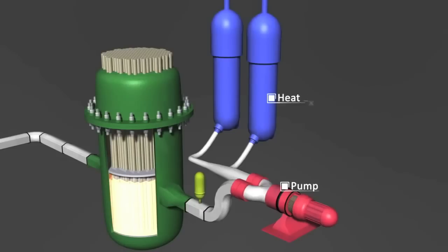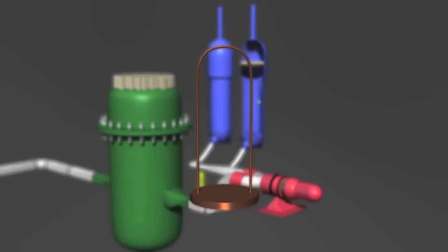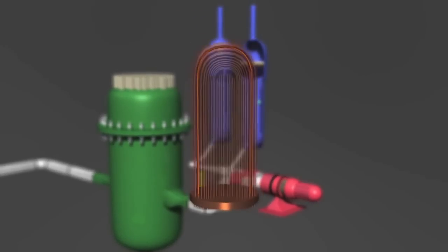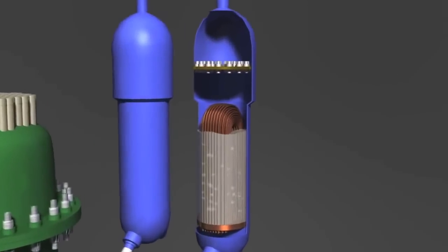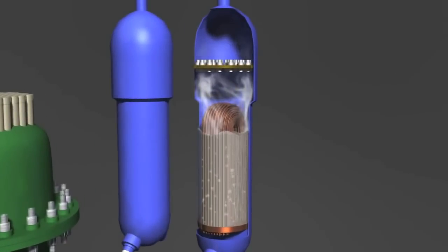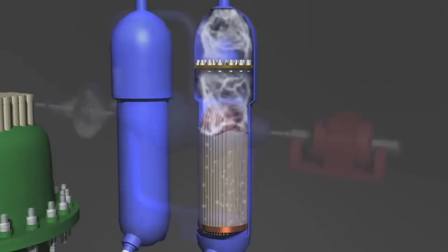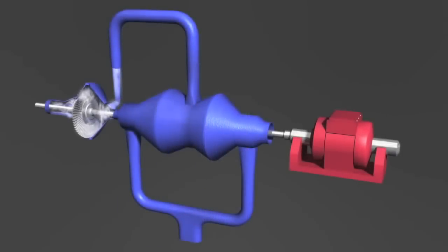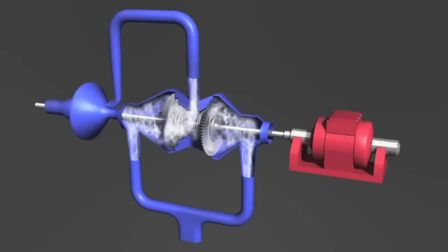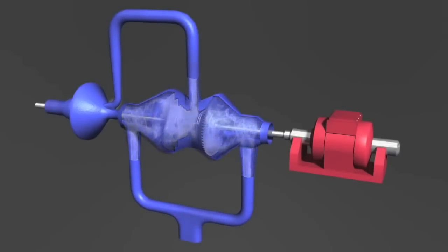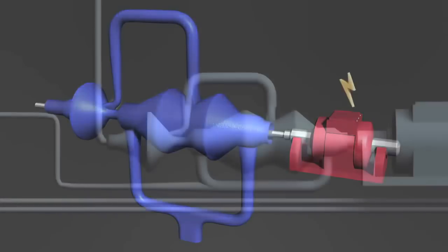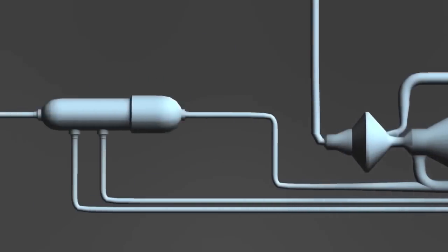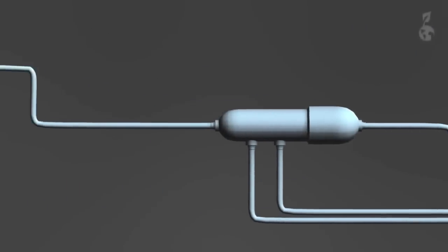The heated water is pumped to a heat exchanger, which generates steam, since any water that comes in contact with the heat exchanger will absorb the thermal energy. The steam that is produced is then directed to the turbines. The first one is generally high pressure and the next two are low pressure turbines. All of the turbines are connected by a shaft to the electricity generator, which produces electricity from the shaft's rotational energy. The steam is then converted to liquid form by a condenser and returned to the steam generator.